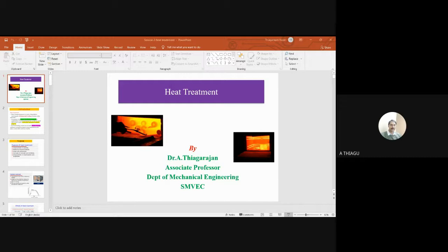So this is practically how the pack carburizing process is carried out. Is it right? So this is our steel sample. You can take it as a low carbon steel, and it is fully mixed with the charcoal material, and the energizer of sodium carbonate and barium carbonate is used. So what will happen? This energizer helps to liberate more carbon from the charcoal. So the carbon is deposited on the steel material. This is a furnace where we have to maintain 952 degrees centigrade for 6 hours duration. So all the carbon is deposited on the steel material.